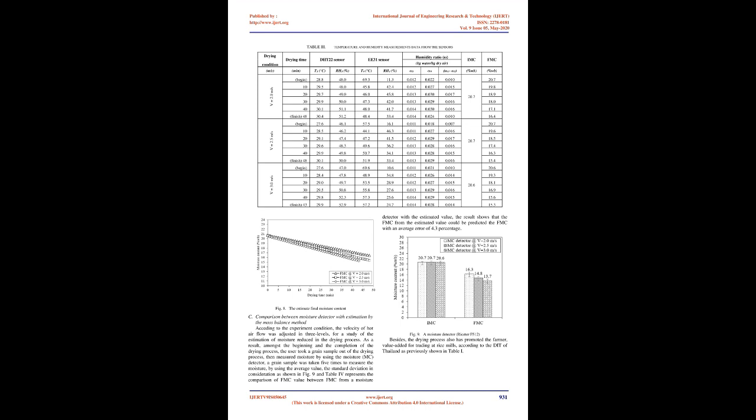As the velocity of air increases, the mass flow rate would also increase as explained in 2. As a result, heat and mass transfer occurs. On the heat transfer side, the temperature of hot air at state 4 would gradually increase, and mass transfer occurs between the mass of hot air and the mass of water evaporated from the paddy grain, as shown in Fig 5. The mass of water evaporated from the paddy grain is absorbed by the mass of hot air flow, therefore the mass of the paddy would be reduced.